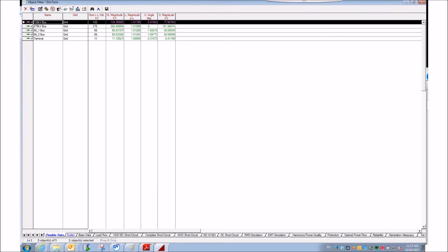Something to note is that in the flexible data window, the variables listed here are specific for terminals. Data objects that are different to the terminal, such as transformers or lines, shunt elements, PV systems, anything at all that has data calculated for it, will have different parameters and can all individually be set up to show different parameters such as line loading, copper losses of a transformer, etc.